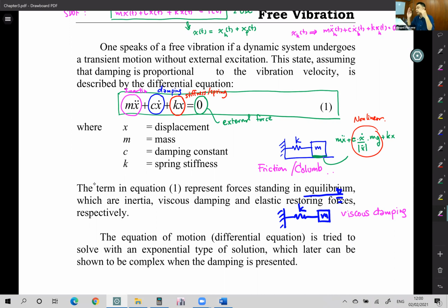If I apply a force of 10 kilonewtons and my building moves like this, and if I apply the same force function but the magnitude increased 2 times to 20 kilonewtons, it will go exactly like the previous motion, but the amplitude is 2 times. Because our system is a linear system.